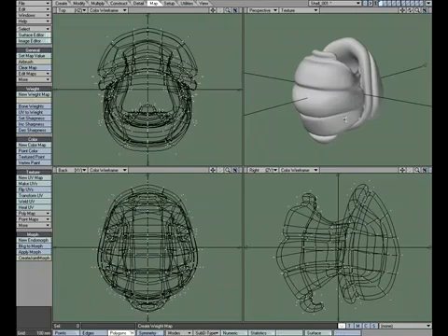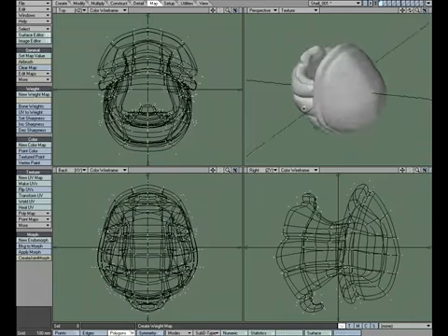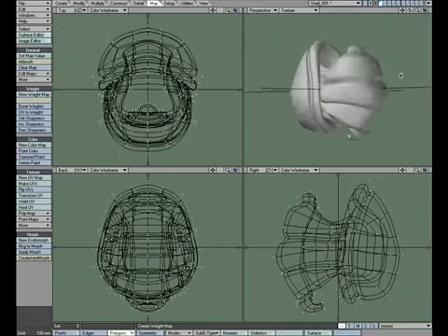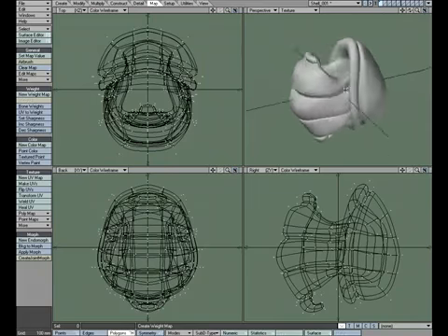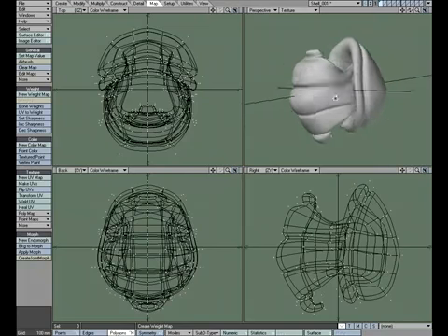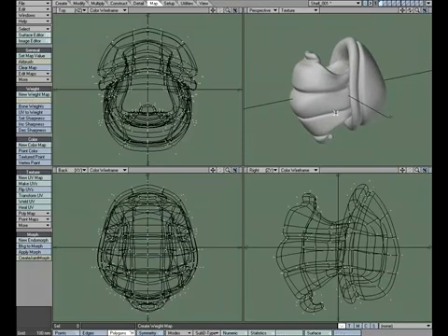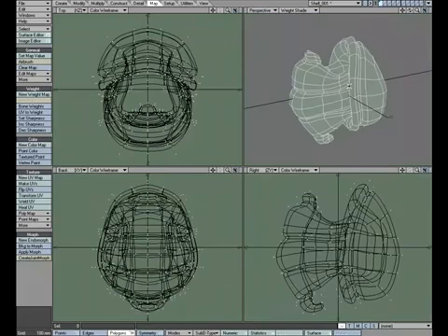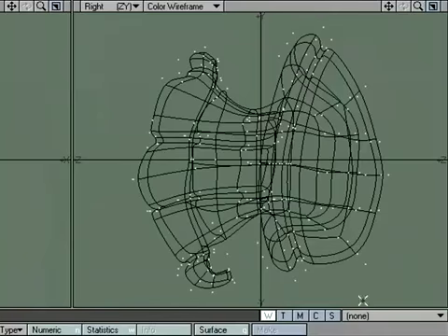Let's take a look at using multiple bump maps on one surface. I've got this model of a shell, and what we'll do is apply a few different bump maps to it, but we'll keep it with only one surface. One way I can go about doing that is to use weight maps. So I'm going to go ahead and switch to weight shade.